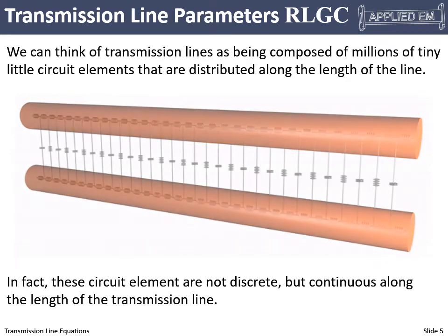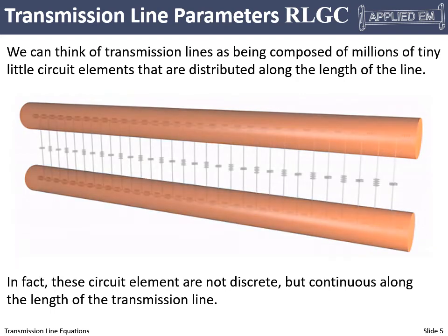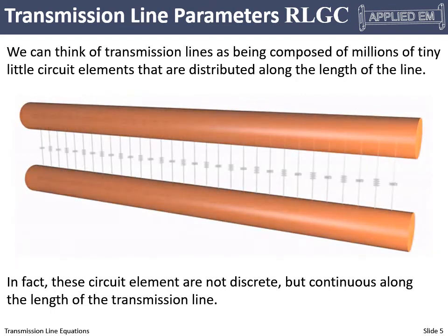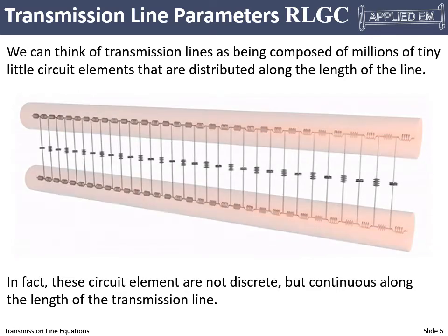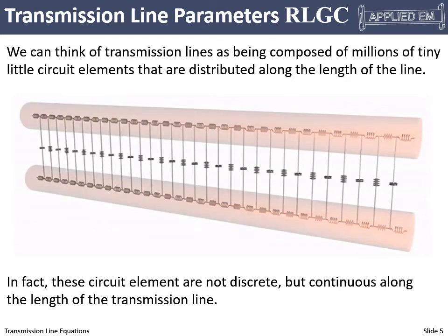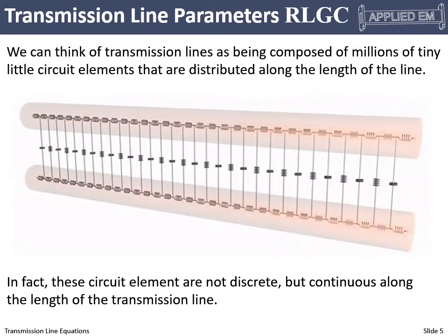And we can start to think of a transmission line as just this series parallel network of resistors, inductors, and capacitors. They're definitely not discrete components, but you'll see that we soon will treat it like discrete components, but they're smeared, smooth, distributed across the transmission line. Very difficult to visualize, and this is really the best I've done at trying to convey that point.